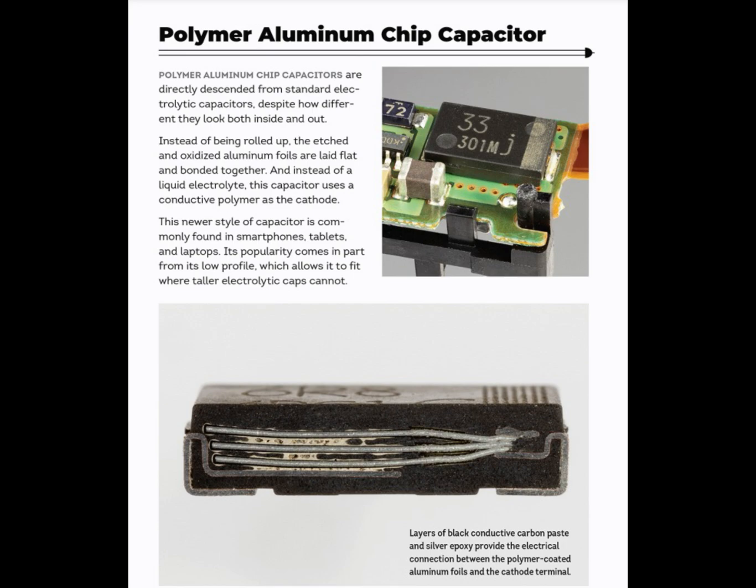They have longer lifespan, which tends to enhance reliability and longevity compared to liquid electrolytes. They are commonly used in smartphones, tablets, and laptops for decoupling and filtering, ideal for input and output smoothing in DC converters and power management modules. They are used in automotive electronics for power supply and signal processing.